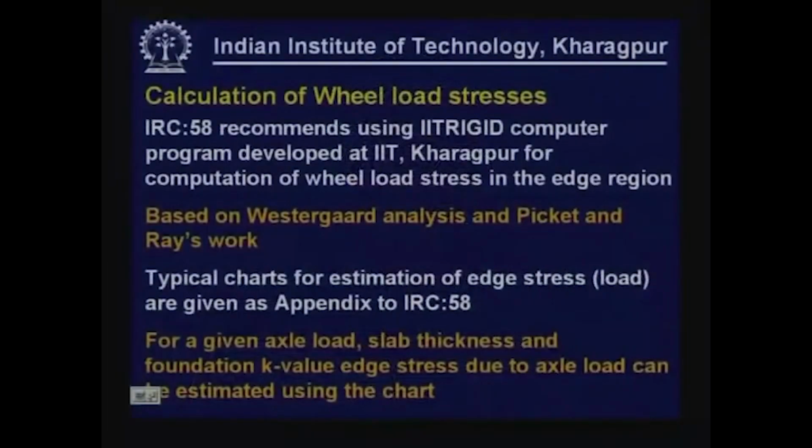This computer program gives wheel load stresses in the edge region because of application of single axle and tandem axle loads. It is based on Westergaard's analysis and Pickett and Ray's analysis. For those who do not use this program, typical charts for estimating edge stress due to wheel loads are also given as an appendix in IRC 58.